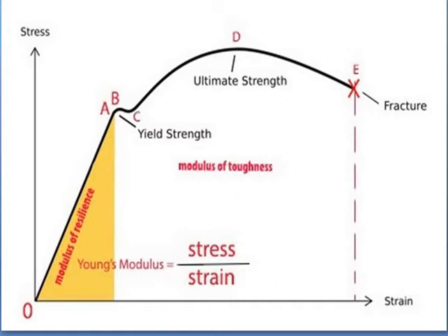The figure shows a stress strain curve. The mechanical properties are commonly determined from a standard tensile test. The testing machine is called universal testing machine. The test consists of gradually loading a standard specimen. When the standard specimen is gradually loaded, the corresponding values of load and elongation until the specimen fractures will be noted down. The load is applied and measured by a testing machine.